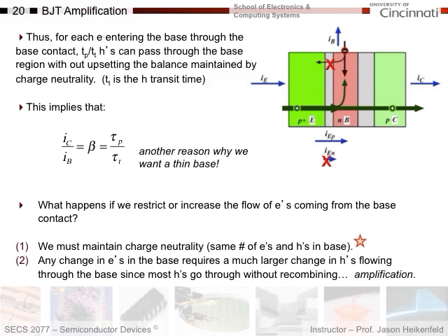And so that will be basically the rate at which electrons are recombining. But here's a key substitution I'm going to do. Okay? Remember that the electron and hole lifetimes are equal. Okay? So when an electron recombines, a hole recombines as well. And so the tau for an electron is equal to the tau for a hole.